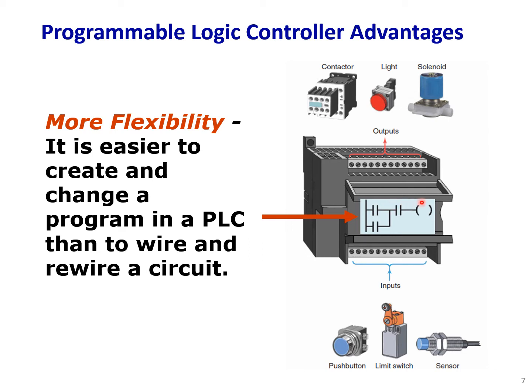You see that this program replaces all of those wirings, and since we don't have the hard wiring, it's easy to change the program and download it to the memory of the PLC. But if we want to change the logic in a relay logic circuit, we need to change all the wirings.